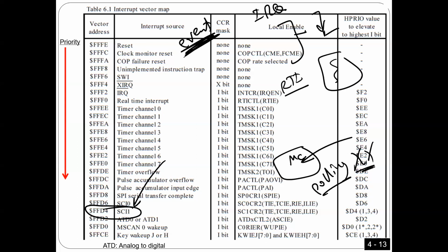The other idea is once you receive data, you trigger an interrupt. That means when there is an interrupt coming from the serial communications, the microcontroller is telling you, I have received the data, please come and take it. That's it. Okay, you got what I'm saying, guys? So I don't need to do polling. I don't need to check if I received the data or not. All that's going to happen is, once the microcontroller receives data using serial communication, all you have to do is go to the subroutine and write code in the subroutine just to take this data.